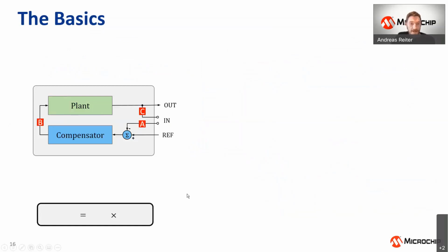So the compensation game, the loop we're going to design now offers a couple of access points where we can basically slice down the problem and observe any component in that system separated from each other. By default, in a classic loop measurement, we're just injecting here. The error signal will travel around the complete loop, and then we will see the response, sorry, at the low impedance side of our injection point, directly at the output.